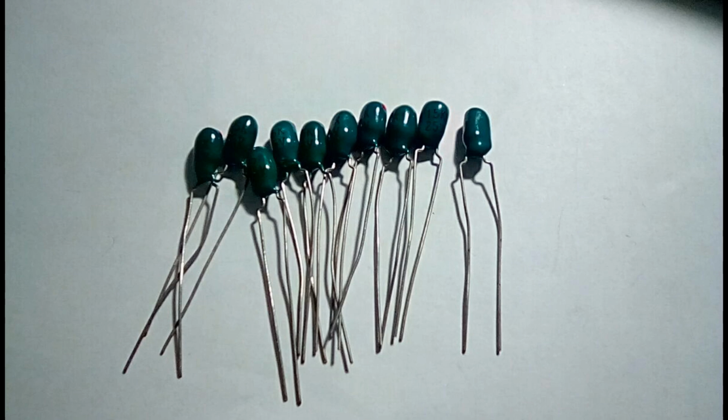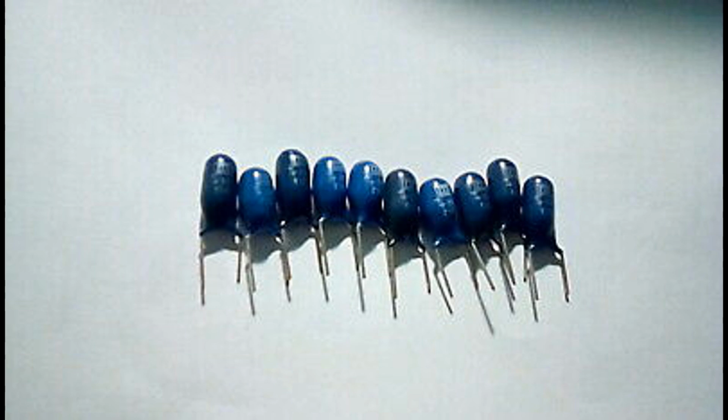5. Excellent filtering and decoupling capabilities. Voltage smoothing. Tantalum capacitors are effective at filtering out noise and smoothing voltage fluctuations, especially in power supply circuits. They ensure stable power delivery to sensitive components like microprocessors and memory chips. Effective at high frequencies. Their low ESR and good frequency characteristics allow them to perform well in high-frequency filtering applications, such as RF circuits and switch-mode power supplies, SMPS.